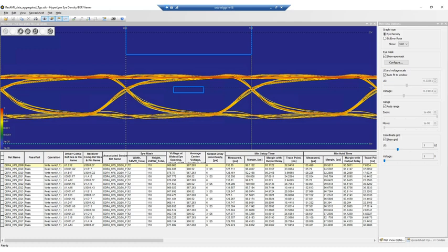Remember, we use the advanced solver to create this power-aware model and have introduced additional PDN effects such as return current, cavity coupling, and via coupling. By passing with these real-life effects in our simulation, we are in really good shape here and can say that the board is verified for electrical sign-off and ready for manufacturing.